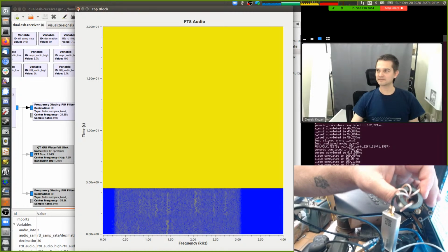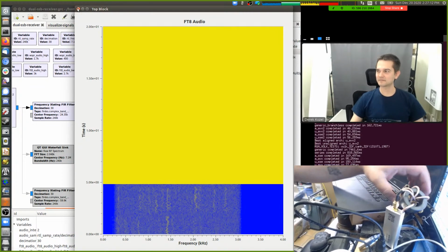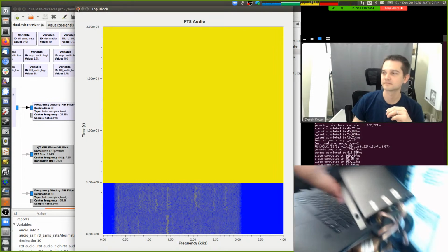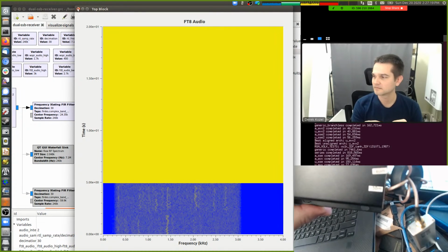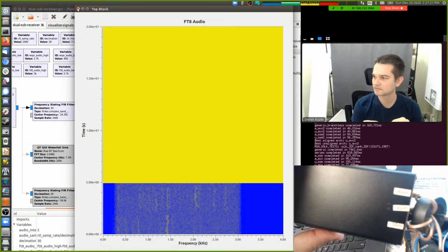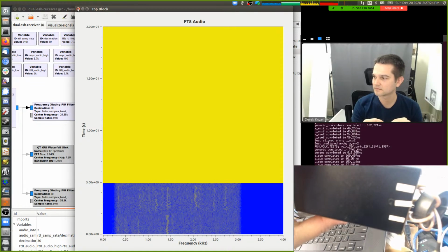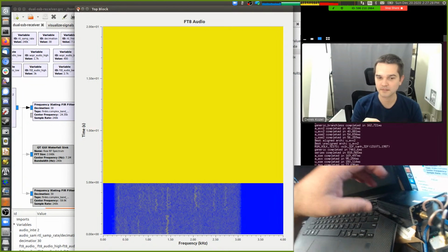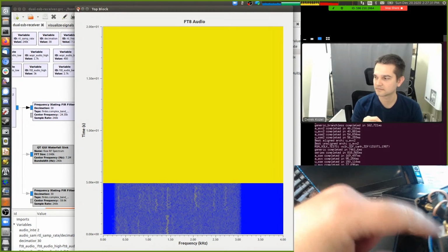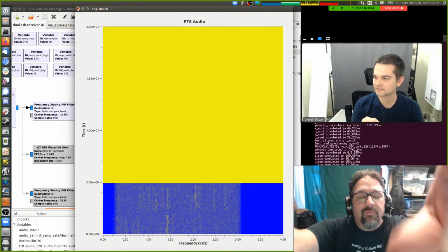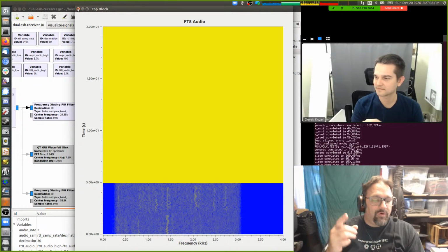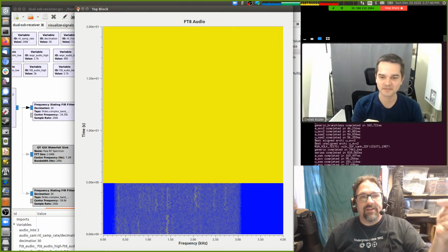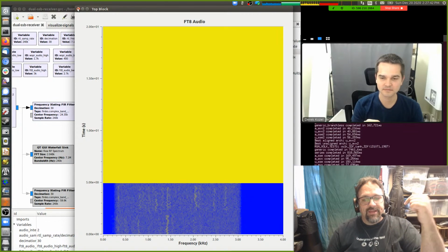I tried a little bit of choking on the interlink between it and a triplexer. This is a triplexer for 80, 40, and 30 meters. I don't know if you can read those numbers at all. Anyway, it's a triplexer, and I've got it hooked up to an outside antenna, and I got the 40 meter going into my RTL. I have on the way another triplexer for 20, 15, and 10. My goal is to have a wideband RF receive antenna come in.